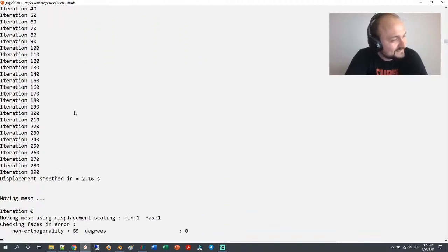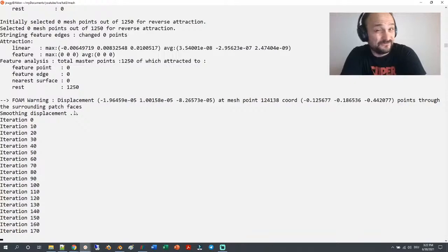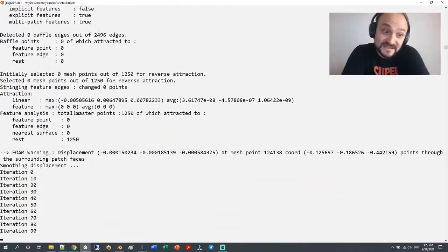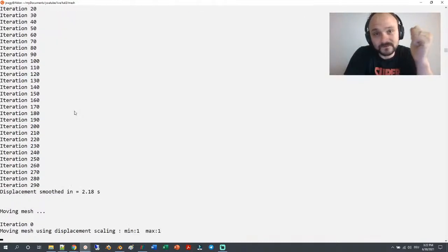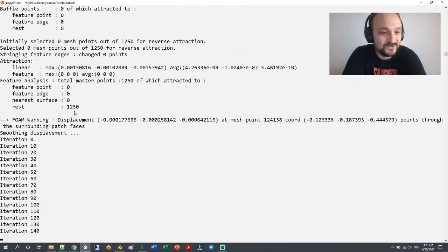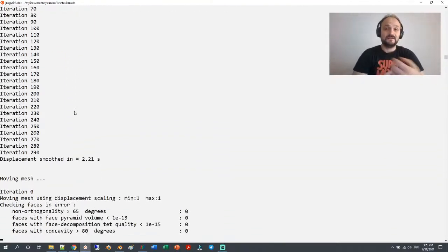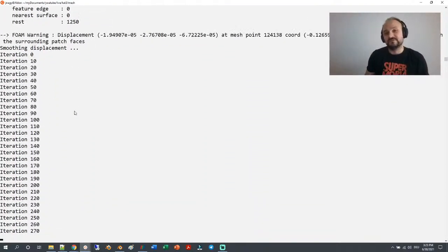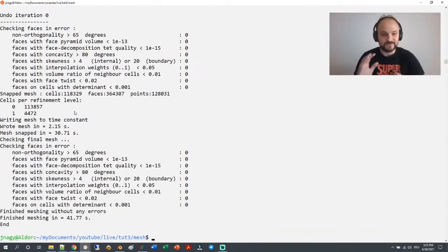I guess the final mesh will be finished once we have the first simulation results, because that's the drawback of turbulent flows: you never know the y plus value from the beginning, especially if I want to try out different Reynolds numbers. So maybe we'll need different meshes for different Reynolds numbers, but we'll see.